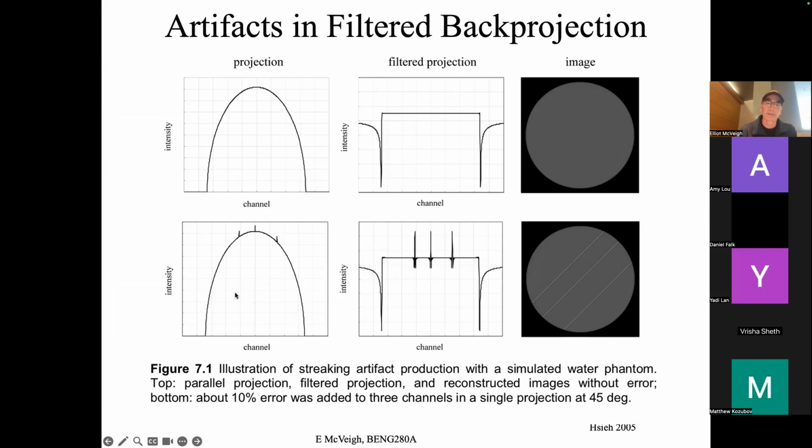What happens if for one specific theta, say I have 1,000 different projections, different thetas, right? If at one of those thetas something untoward happens, in that a device on the patient or something lets off an electrical pulse or a spark or something like that, or one of the detectors glitches and has some extra voltage. So in one view, we get these little spikes on our projection, and these are artifactual. They're not actually in the object, right?